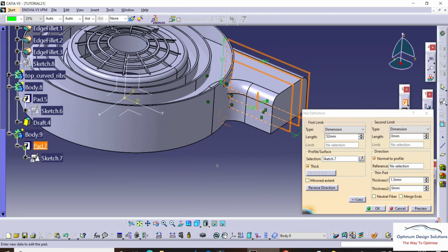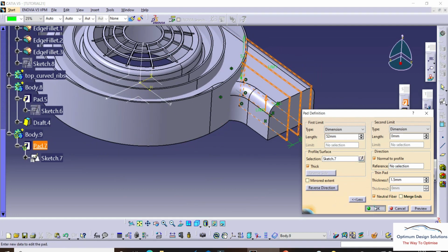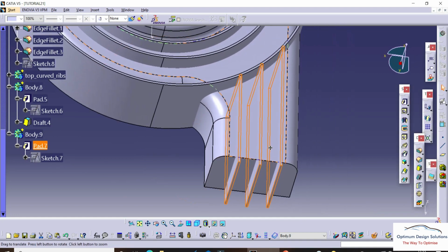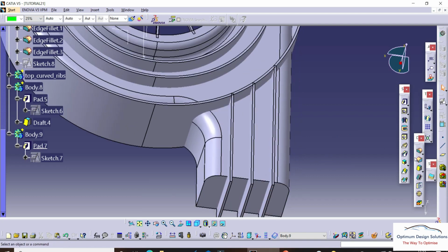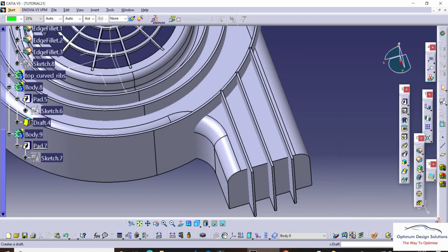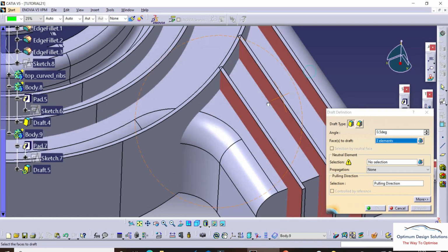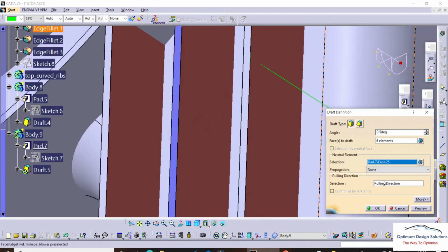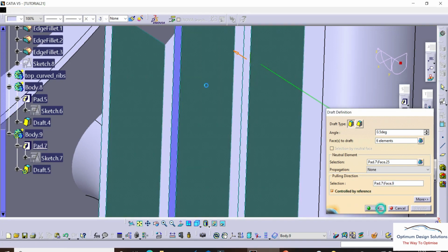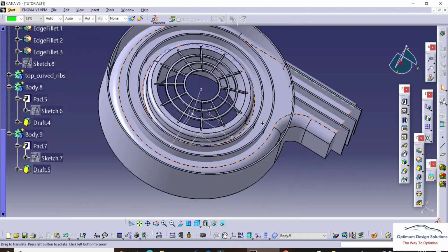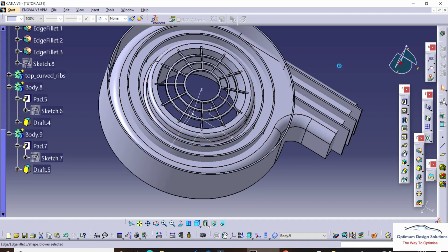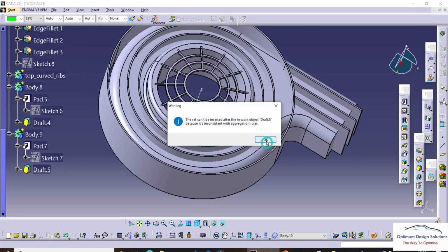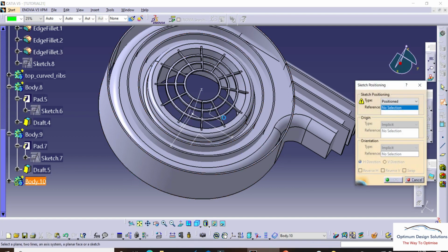A sink mark comes at the area where the thickness increases, so insufficient cooling happens during injection molding, and that's why that particular defect comes. In the next part of this video we'll cover the manufacturing defects, the probability of a manufacturing defect for this particular part.